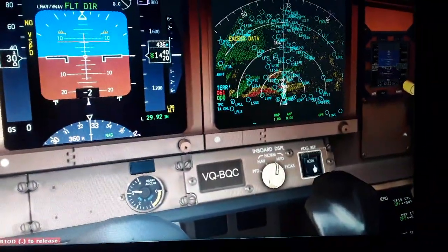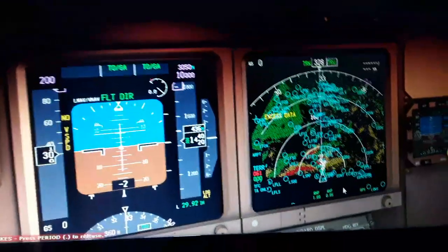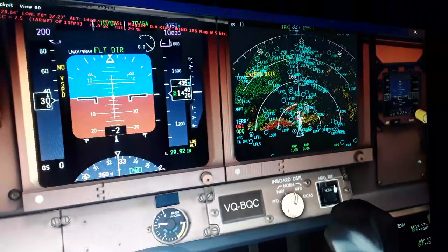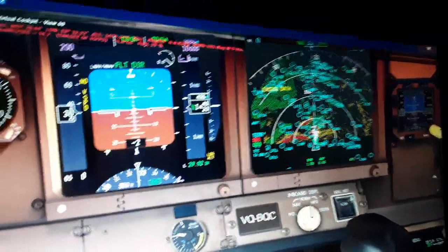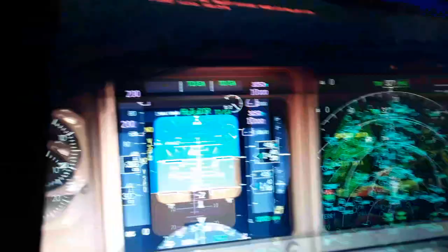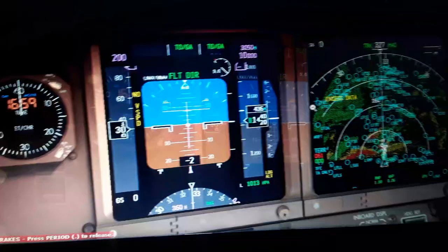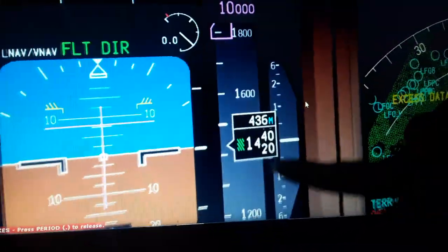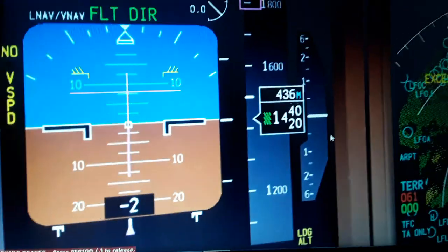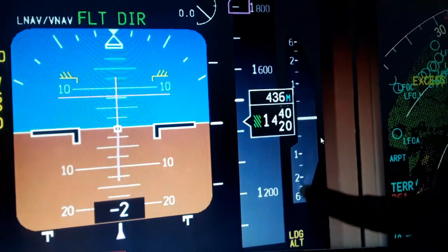So you can see it's either magnetic or geographic north pole right now for navigation. So we change back to the normal magnetic, and we have also inches of mercury or hectopascal. So we see 1013 hectopascal. You can see here the vertical rate of climb and descent of the aircraft in feet per minute. So you will see the needle moving up, the aircraft is climbing,